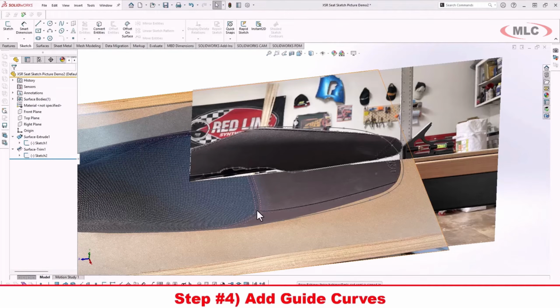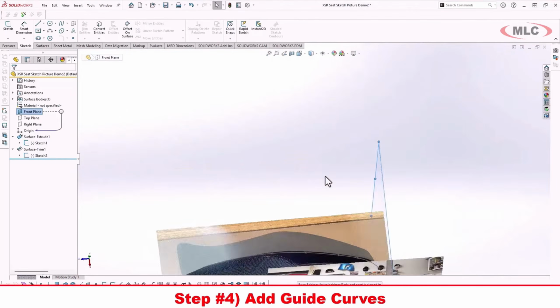It helps to plan out how these surfaces are going to be broken up and how it may make it easier to work on later if you have to make adjustments. So I decided to use those fabric seams again and break the curve up into two separate surfaces along that one main seam. And I'll use guide curves at the front where those seams intersect and one at the back where the seams intersect.